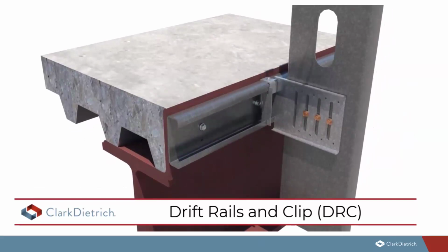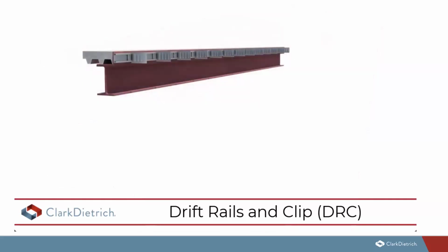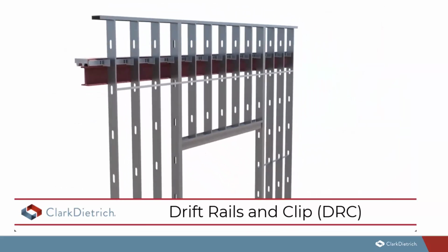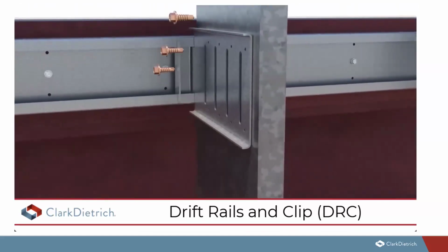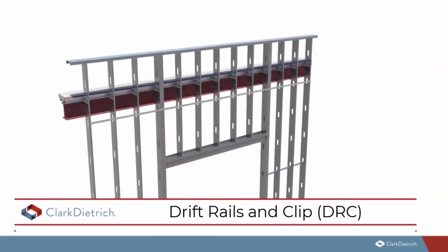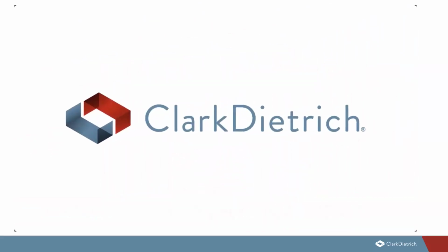So here we have the locking angle or stopping clip that's going to restrict that lateral movement. And here we see the screws being installed into the holes instead of the slot. So again, this is very popular with panelized construction because the clips can actually be installed from the inside of the building, and the stud framing can be tilted up to be installed to the building structure. And again, I apologize that there was no audio on that. If you have any questions, feel free to reach out to me and I can share it with you.